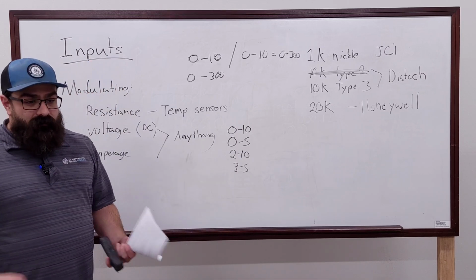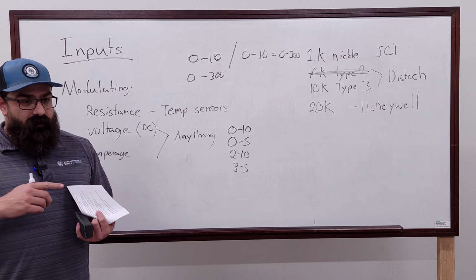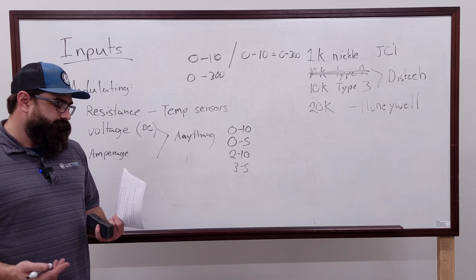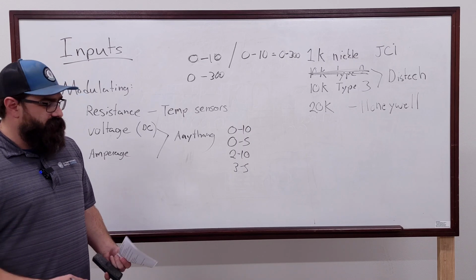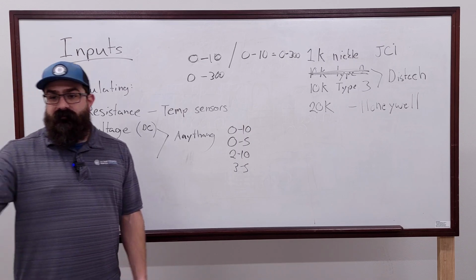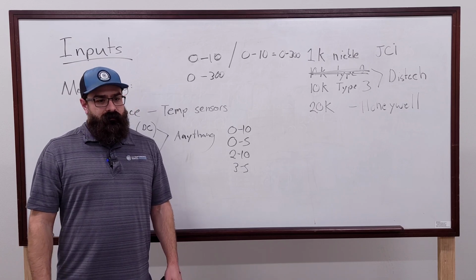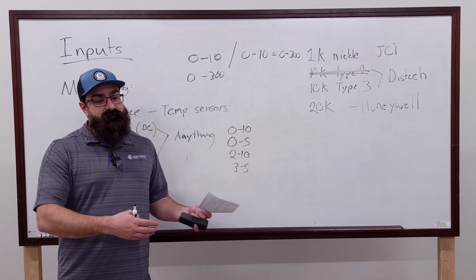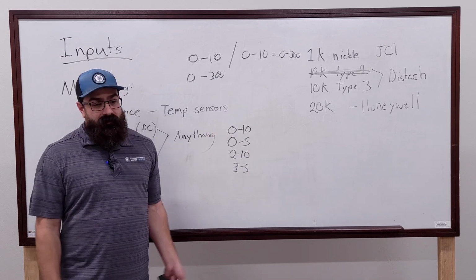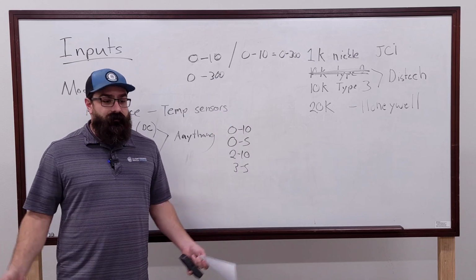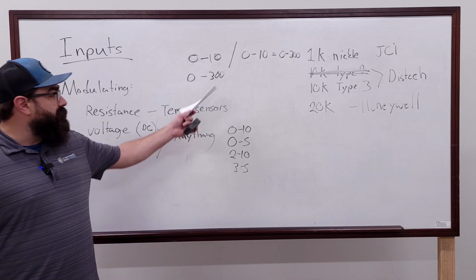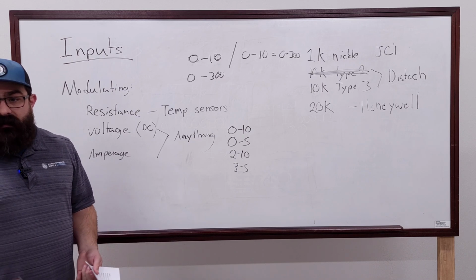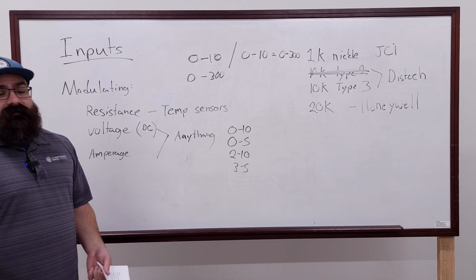But I can do that with anything. I can do that with pressures, temperatures. I can do it with a float sensor in a well. Whatever you can. If you got a sensor that'll put out a 0 to 10, I can scale it in an input and monitor any value at that point. Because once it's broken down to just a 0 to 10, all I need is a way to configure that in the system. I can do electrical meters.